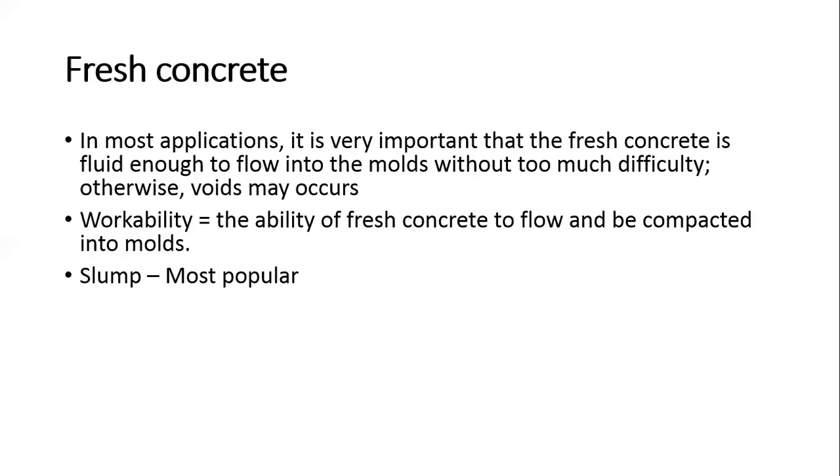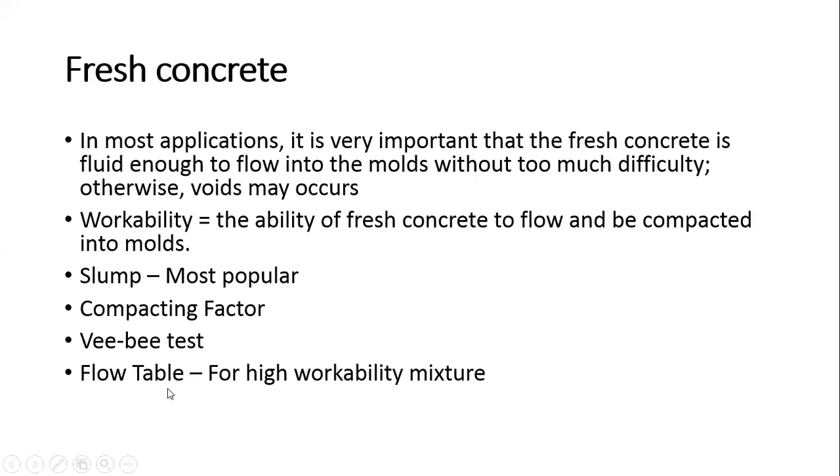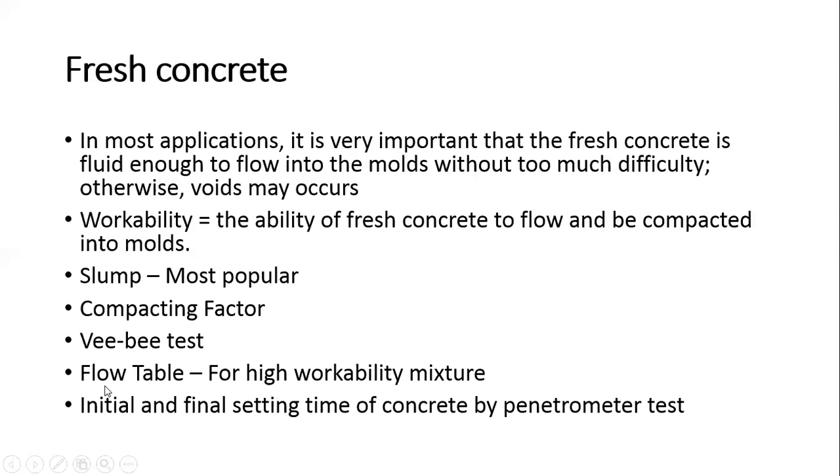Now, the tests available for fresh concrete are the slump test, which is the most popular, and the compaction factor test. The first two tests you have already performed in your secondary classes, so we'll discuss them briefly here. The third is the flow table test. For high workability mixtures, we adopt the flow table test. And we have one more test, the initial and final setting time of concrete by penetrometer test.